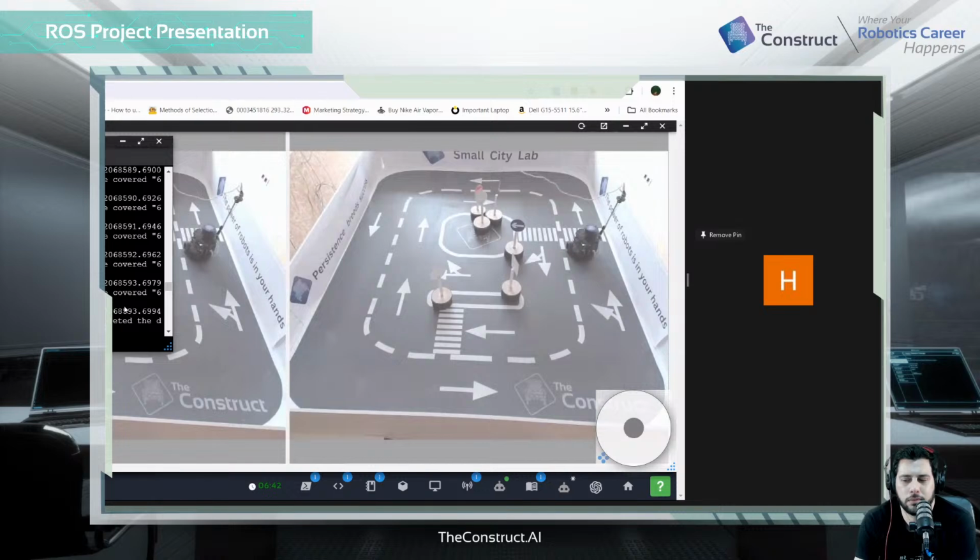Basically, in the first wall following function, I used the diagonal values and the right values and kept it at a distance between 0.3 and 0.25, and didn't want to go too fast because it would not follow it properly. It would go too much towards the wall or too far away. Why do you think that is?